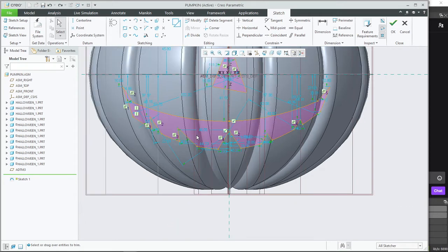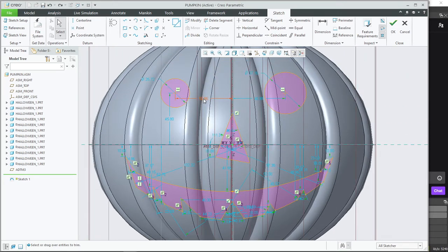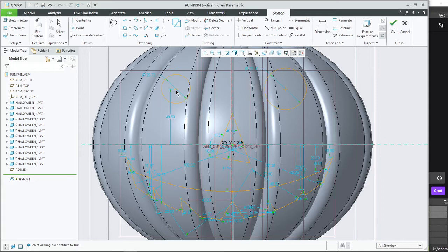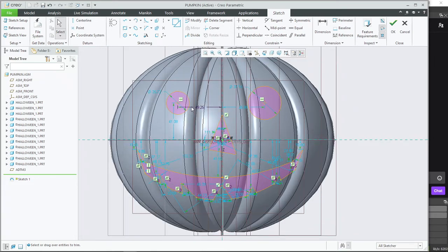Ah, and that's... However, if I actually fix a dimension, like say this is always 50, I can do whatever I want to this circle, but it will move only in the directions the program is allowing it to, not everywhere. That's the advantage of constraints. Right. Very interesting.